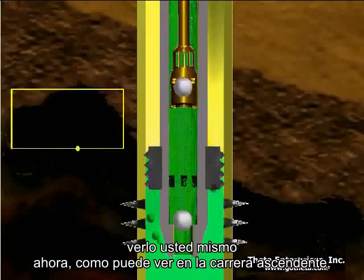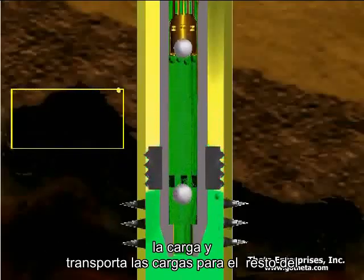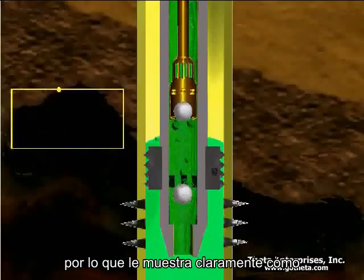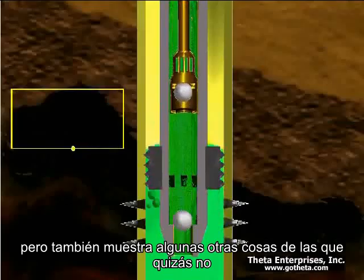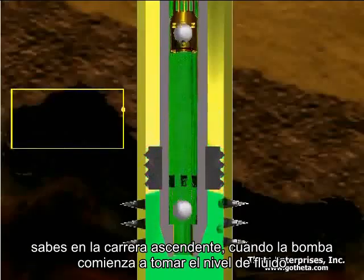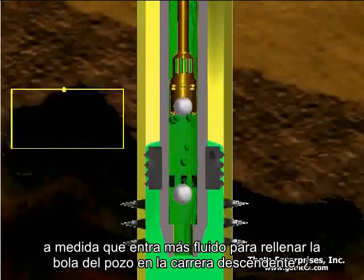As you can see on the upstroke, as soon as the plunger starts to move up, the traveling valve closes, it picks up the load, it carries the load for the rest of the upstroke, and then on the downstroke it releases the load. This is a full pump with no mechanical problems. So it clearly shows you how the pump works, but it also shows some other things that you may not be aware of, and that is how the fluid level changes. In the upstroke, when the pump starts to take the fluid in, the fluid level in the wellbore goes down a little bit, as more fluid comes in to refill the wellbore on the downstroke.